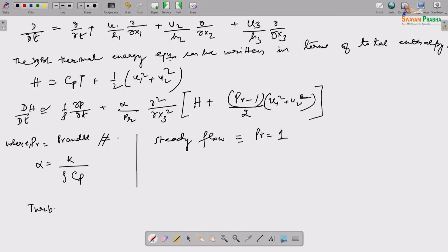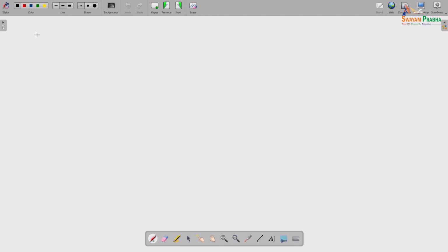We are now going to really talk about turbulent boundary layers, begin to talk about it in 3D. Essentially, we are looking at the 3D turbulent boundary layer equations. So look at high aspect ratio bodies. What are the high aspect ratio bodies? Swept wings.